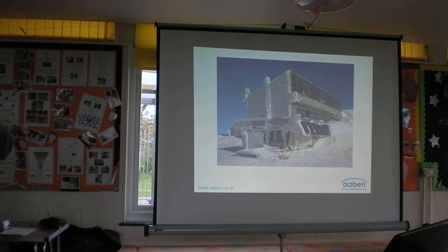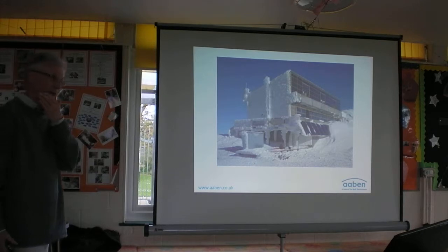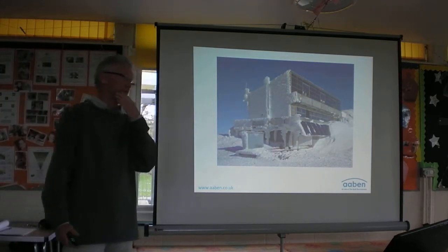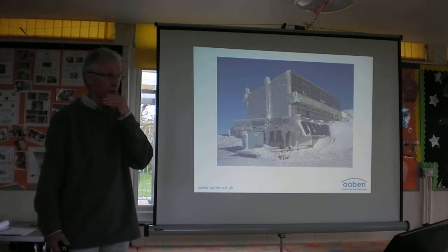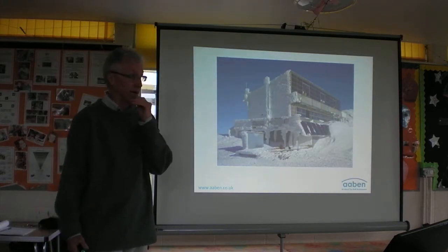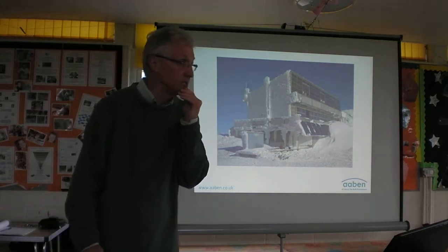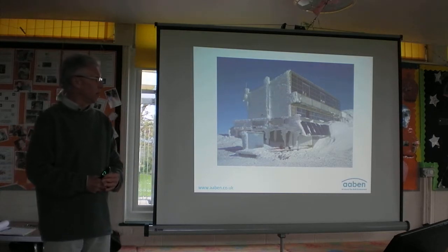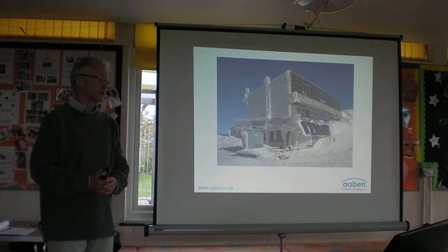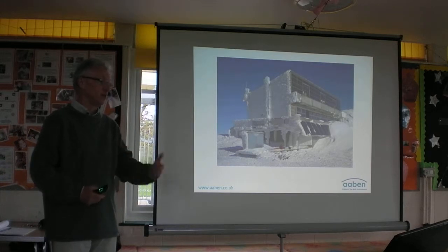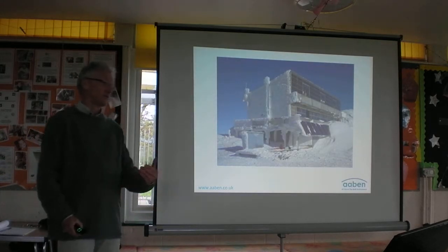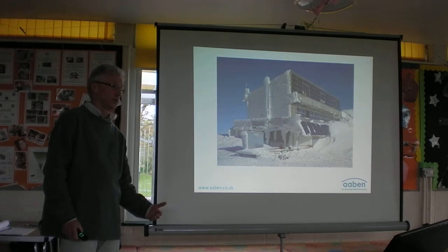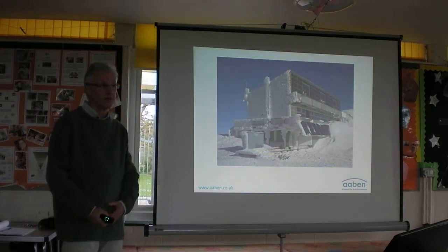It benefits the occupants. A lot of passive houses in Germany experience 20 degrees below zero outside, and the heating only comes on when it gets to sort of minus 15. We designed to 20 degrees inside, so you're talking about a delta T of 40 degrees difference. The heat losses are so low that quite often the heating is only coming on at that sort of minus 10, minus 15, minus 20 point, which, if you think over here, we don't often experience.